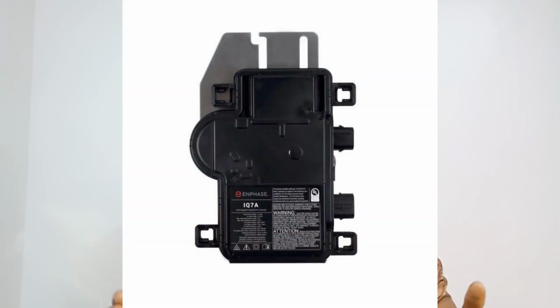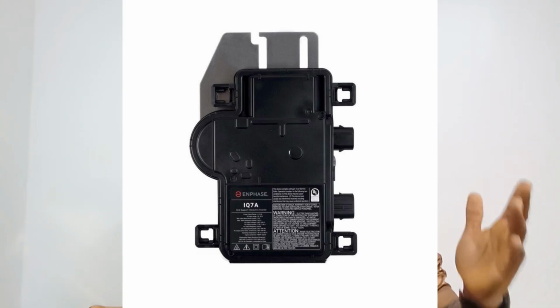Then the second type of inverter is the micro inverter. A micro inverter converts DC electricity from the solar panel to AC electricity at the roof level. So with a micro inverter, you don't have high DC voltage running on your roof or your ground mount. The micro inverter also helps with shading and complicated roofs, so that when one panel is shaded, it doesn't affect the output of other panels. It also helps with panel level monitoring, so that you can monitor the production of each panel independently.